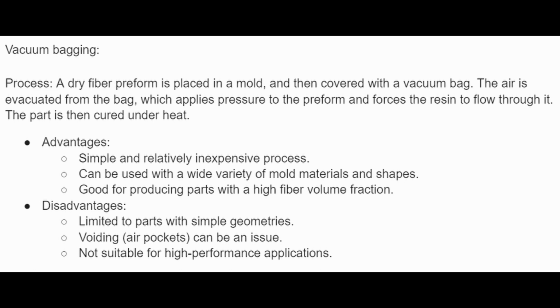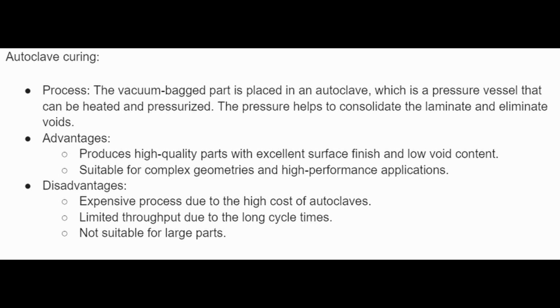Advantages: simple and relatively inexpensive process. Can be used with a wide variety of mould materials and shapes. Good for producing parts with a high fibre volume fraction. Disadvantages: limited to parts with simple geometries. Voiding, which is air pockets, can be an issue, and not suitable for high performance applications.